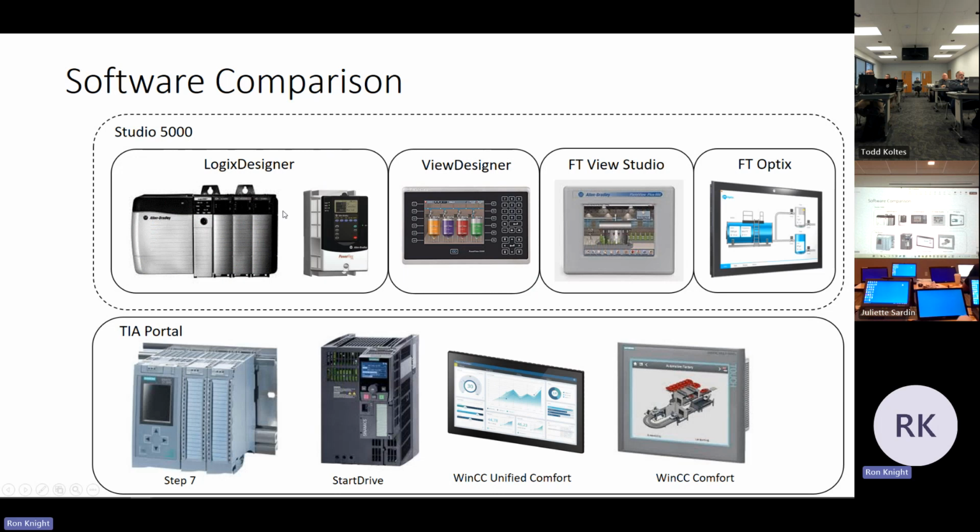They're a natural gas facility in Louisiana, but they didn't really care for any of the HMI offerings. And so they ended up standardizing on the WinCC Comfort panel. This was before the Unified was out. I need to talk to them about stepping up to Unified. Anyway, they standardized on Comfort, and I'll show you later today how easy it is to get one of these Comfort panels to talk to a Rockwell PLC.